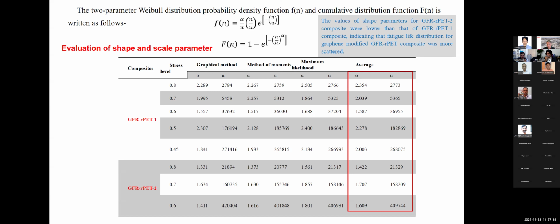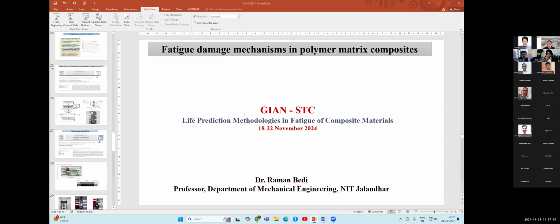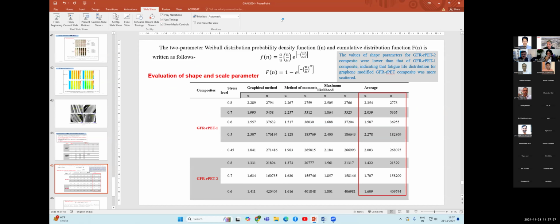The shape parameter typically varies a lot when I compare metal fatigue and composite fatigue. And this, as I said, is a measure of spread. Again, there are formulations and observations from the data that the scale parameter also depends upon the stress value at which you are testing. Normally a large spread is observed at lower stress values, whereas the spread goes to a lesser value when you increase the stress value. So these are the typical takeaways from this topic on fatigue of composite materials.